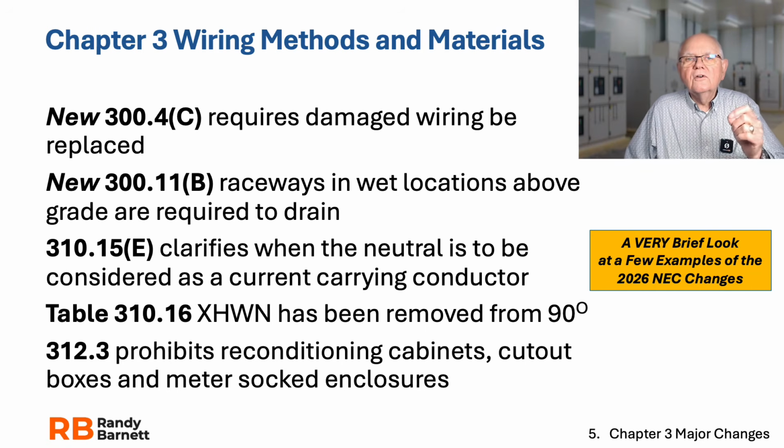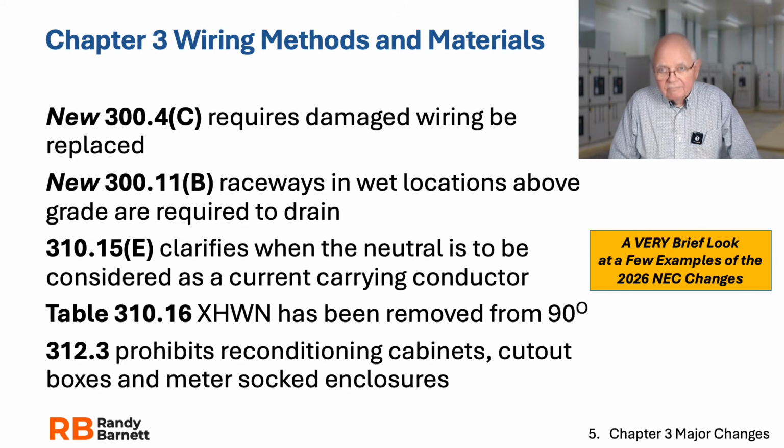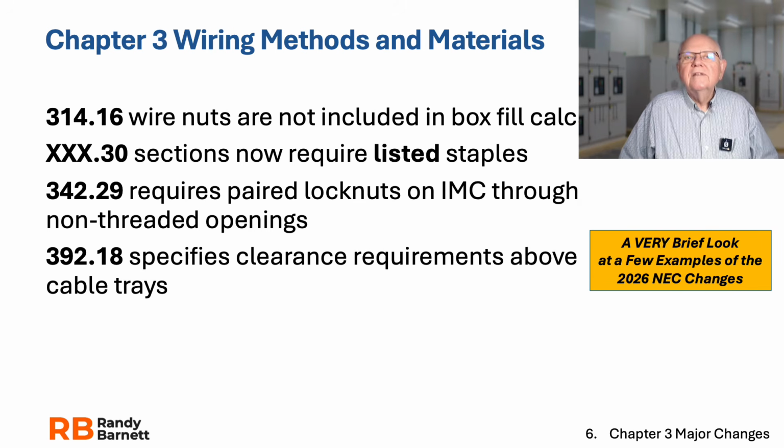312. Let's go to Article 312 on our cabinets and cutout boxes and so forth. And it says I can't recondition cabinets, cutout boxes, meter socket enclosures. So that's a change.